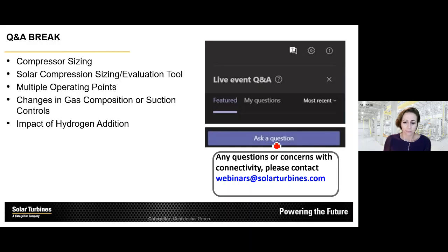Well, it really depends. There are a lot of upset conditions where you, for a short period of time, run in stonewall. A typical example is if you have a brand new pipeline and you start filling gas into it. For a while you will operate your compressor at very low pressure ratio, and if you want to make that filling as fast as possible, you want to maximize the flow. So you're going to run the machine in stonewall. I see. Thanks. So more of an upset condition occurrence.